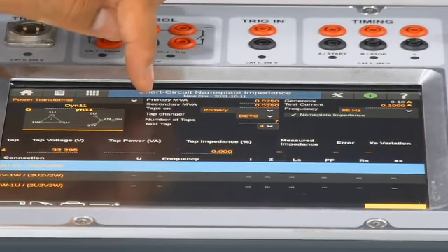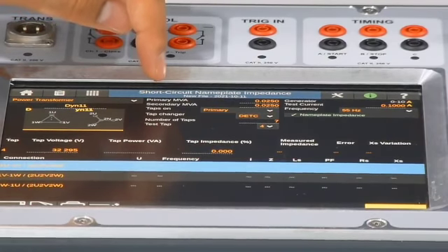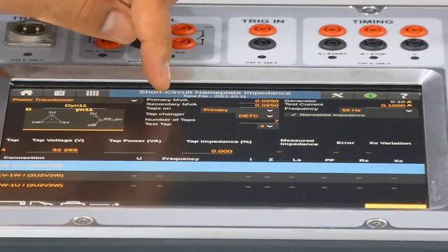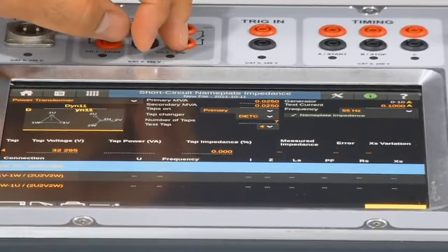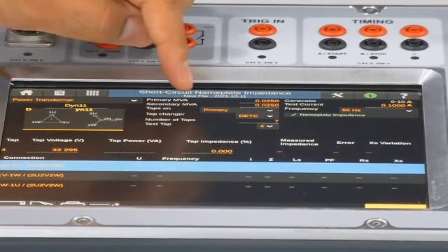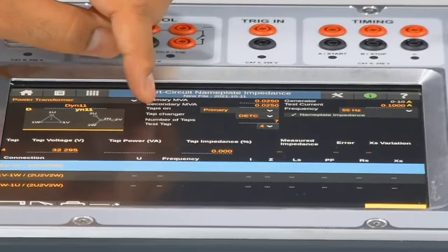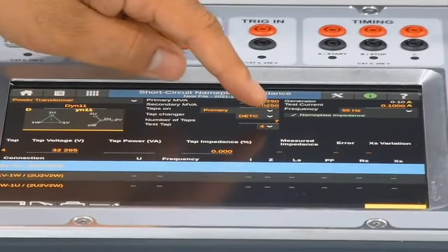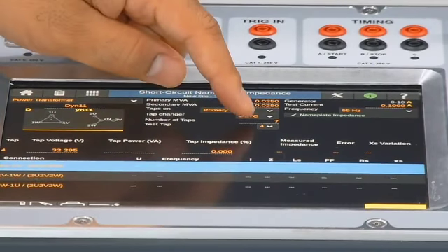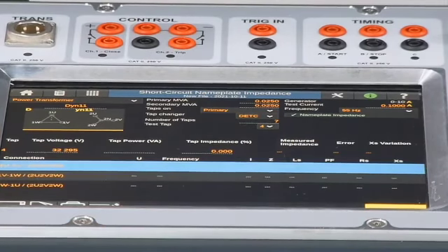It is the same for secondary. For some transformers, the secondary MVA output is different from the primary, usually with a tertiary. My taps on the primary side are correct. The tap changer is the energized tap changer, which is correct. I have 7 taps, and I'm testing tap number 4. I can show you later on my power transformer. I have 3 phases to test.